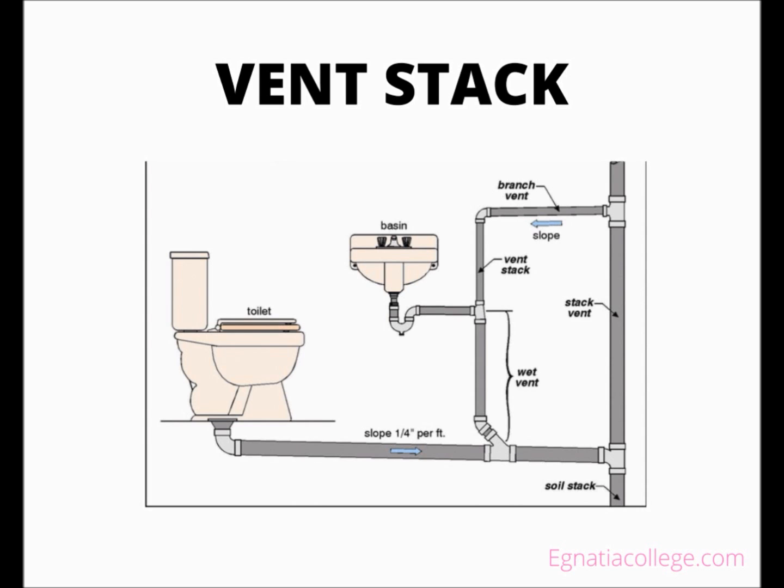Unless otherwise indicated, all vents are dry. Several piping configurations allow a drain to be used as a vent. It is known as a wet vent and is discussed later in this chapter. The size of a vent stack is based on numerous factors, including the total discharge load of a system, which is expressed as drainage fixture units, FU, and the length it travels.